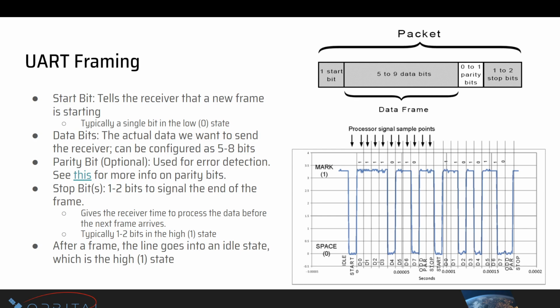Any other questions? Yeah. We use a state machine. Basically, that would be the little module, a little circuit in your MCU, or sometimes it's even an external chip that you can solder on and create wires to connect your MCU to. Usually inside those circuits, there's a state machine running constantly, checking for the start bit and stuff.